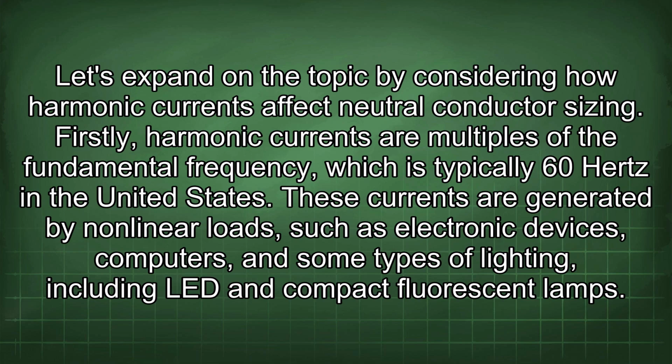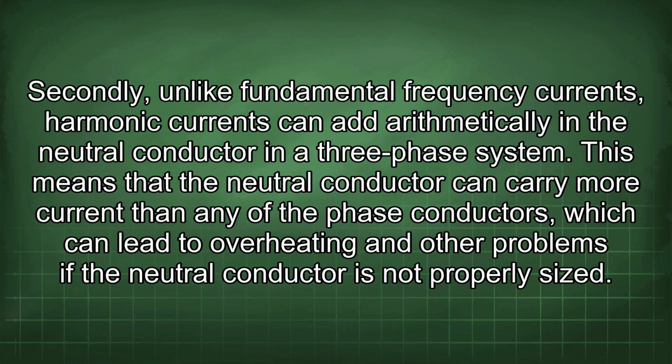compact fluorescent lamps. Secondly, unlike fundamental frequency currents, harmonic currents can add arithmetically in the neutral conductor in a three-phase system. This means that the neutral conductor can carry more current than any of the phase conductors, which can lead to overheating and other problems if the neutral conductor is not properly sized.